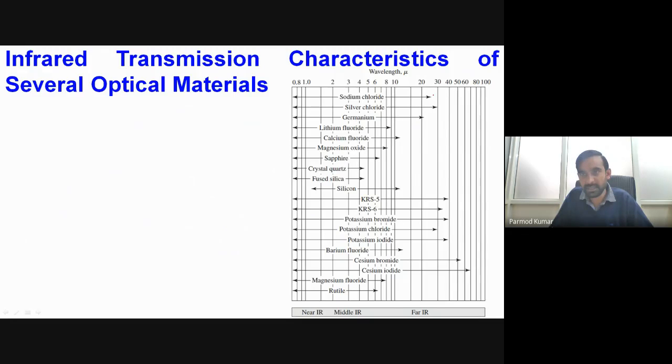Depending upon the wavelength coming from our source, we can choose what type of material to use to fabricate our enclosure, which will hold our main sensing device for determining the value of the corresponding radiative flux. These are the different materials given here, and the spectrum of wavelength within which they allow optical access.